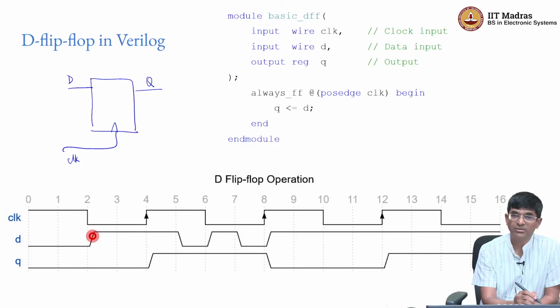One is that D might actually be coming in from somewhere outside the circuit, so it doesn't really know of the existence of a clock, and what you are trying to do is synchronize it, get it in line with the rest of the clock. That's one part of it. But an even more common scenario is that D is the output of some multiple computations happening somewhere else, based on the values of other flip-flops and inputs and so on. As a result, it takes some time for D to change to the value that it has over here. So the bottom line is, there is absolutely no requirement that D must change exactly corresponding to a positive edge of the clock.